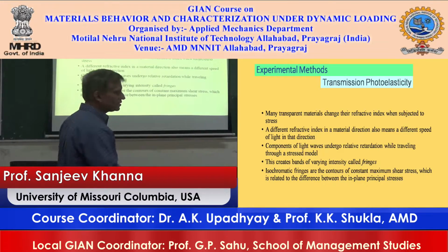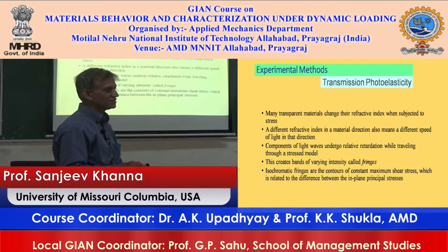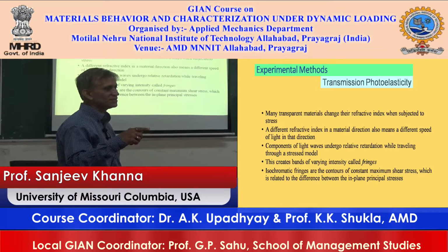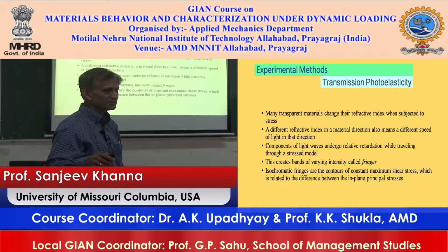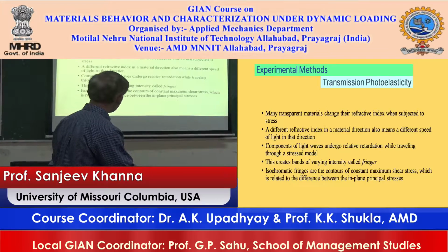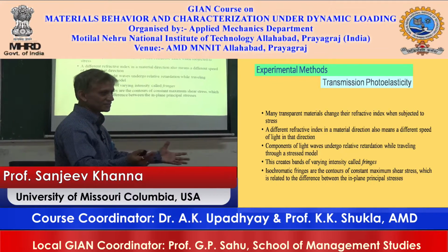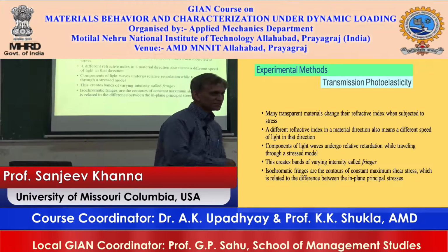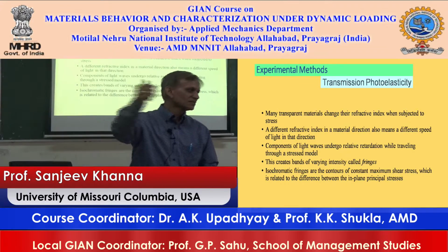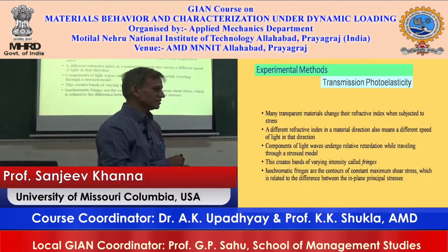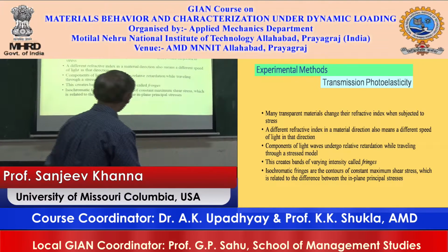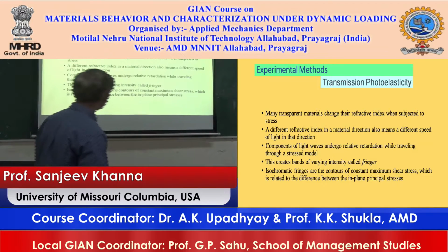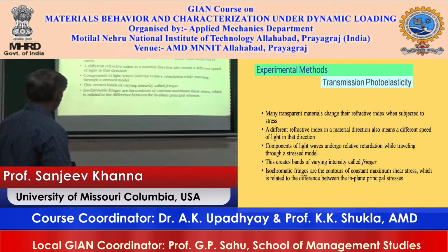Here I have some other sigma 1 prime, sigma 2 prime. In the middle I have sigma 1 double prime, sigma 2 double prime, and so on. So every point has a different state of stress. There may also be contours of stress which are constant. I might have sigma 1 which is constant along a certain contour. That's fine. So what happens then?